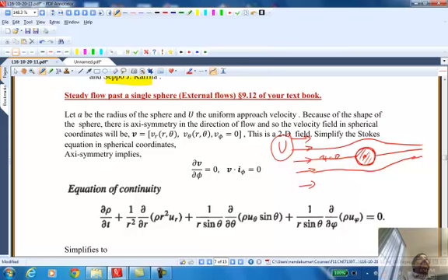But you can take this problem, put it in COMSOL, and get the drag force at a Reynolds number of 400. That's the beauty of a package like COMSOL, because it solves the complete Navier-Stokes equation. But we are going to solve only the Stokes equation, so we are solving only for laminar flow, creeping flow, very low Reynolds number laminar flow. The same problem physically is meaningful at all Reynolds numbers, but we need to develop different techniques for solving them.